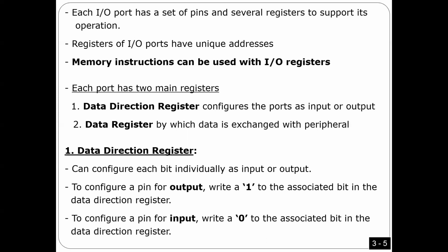So this data register should have an address like a memory location. All you have to do, if this pin is output, is write to a byte that has an address like a memory location, and set some bits and clear some bits. That's what we have been doing many times, right?